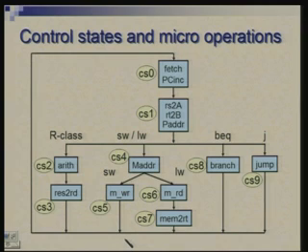All right. So, if you take that view, why not think of a controller as a small computer which executes a simple program, and that program has basic operations which are micro operations, and all it does is generate control signals for the data path. Okay, so this is a program which does nothing else. It does not deal with manipulating data in the main memory, does not deal with the register file and so on. All it does is that it goes through steps. Each step involves generating some control signals for the data path. So with that view,